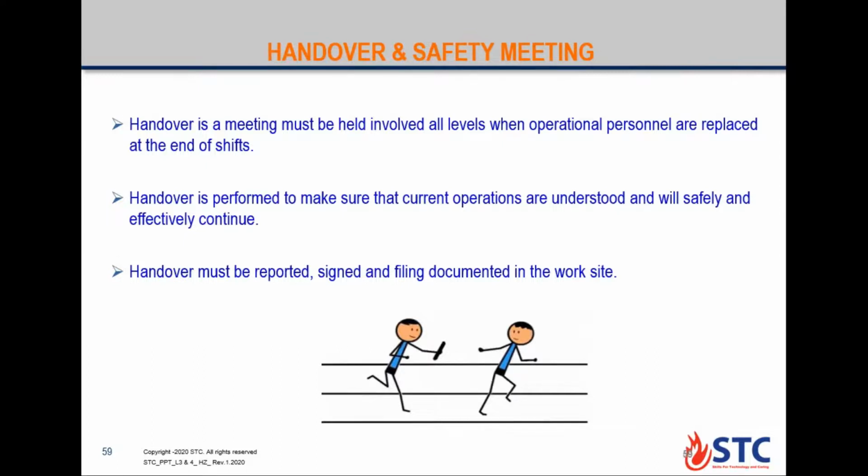Actually, Ahmed, the importance of the handover and the safety meeting is that in the safety meeting we all discuss the risks in the operation that we are going to perform. During the handover, we also tell the other supervisor or engineer that the following operation is going on, so we need to take care of specific calculations. Suppose we are doing the bleed and lubricate method. We must tell the person we are handing over to the pressure trend, in how much time we have to bleed, and how much volume we have to pump.